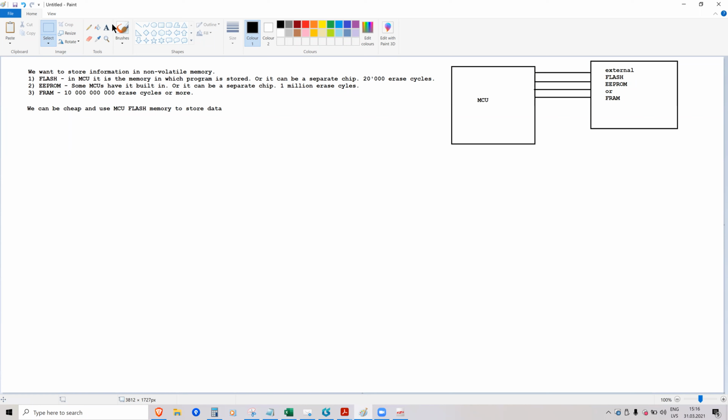This is just how it's built. Because it's hard to write ones and easy to write zeros, because of some electrical implementation, it's easy to discharge something but hard to charge. So it's built in such a way that when you erase, you do the hard work and erase the chip to ones, and when you write something to it, you just clear to zeros.